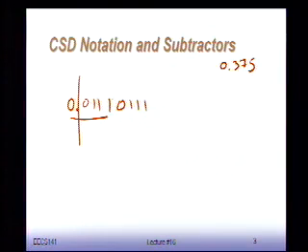I get out of the 8 bits, I get 6 ones. That's expensive. Wouldn't it be nice if I have maximally 4 ones, and maybe a smaller number of them? There's a very simple trick of doing so, and that is basically changing the number system. You know, number systems, you have decimal, you have binary. There's also something which is called redundant binary.